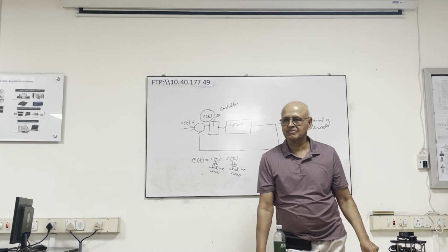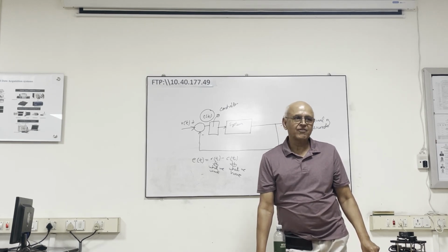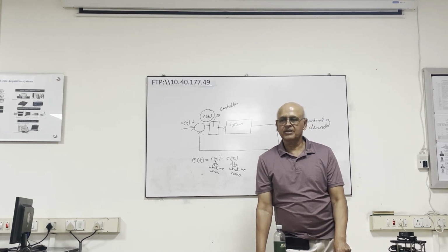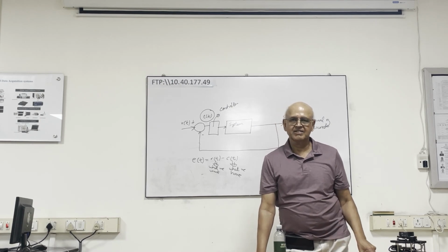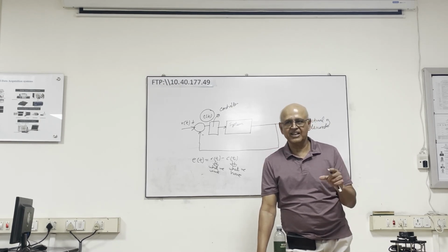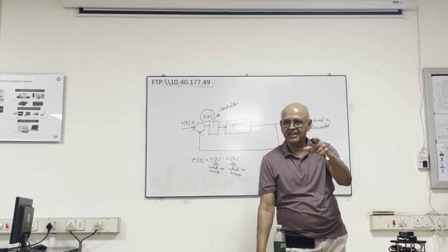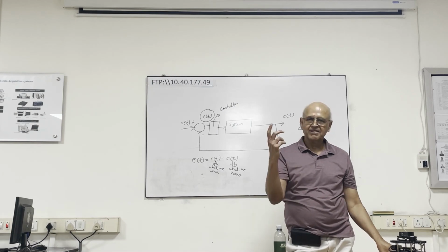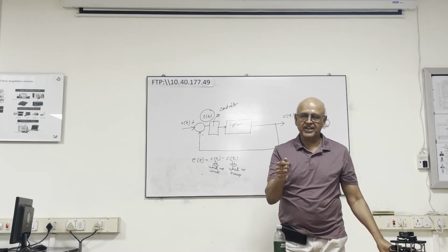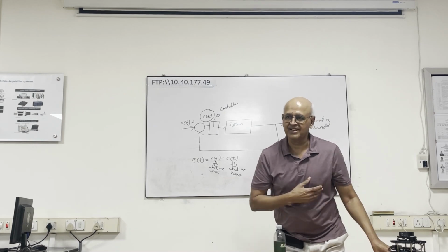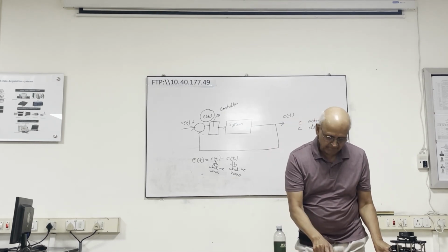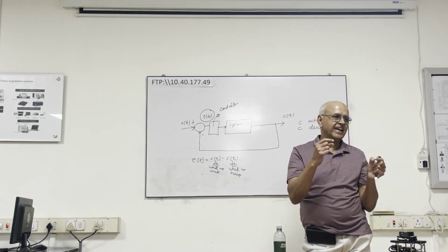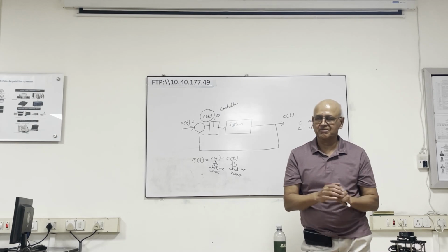Now how would you do that? So you have to do what? You have odometry, right? So won't that allow you to measure the total distance traveled? So that's how you should really do it. Now the program you are implementing for the C, you are still doing open loop. You are saying I'll figure out the different times, but really what you should be doing, and maybe for this particular example it'll be easier, is to graph it, and then maybe you can figure out the lengths approximately, and then you create a loop based on distance and not time.